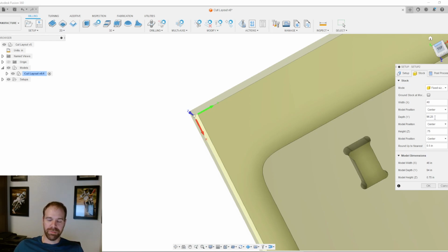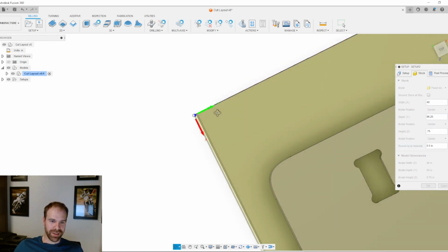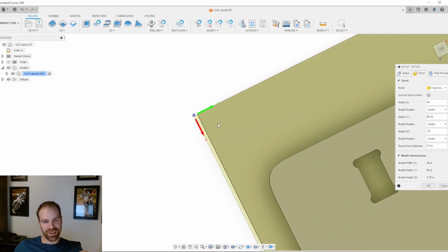a 1/4 inch, then basically if I line the tool up on the z-axis, right, so I touch off this corner, then I hit the home button, it shouldn't drive into the plywood. I think I'm going to actually want to do more like, I don't know, what makes sense here? The 1/2 inch was nice. Let's just stick with a 1/2 inch because that's really going to be fine. Because we don't need to have it cut exactly perfectly on the plywood. I'm going to click OK.